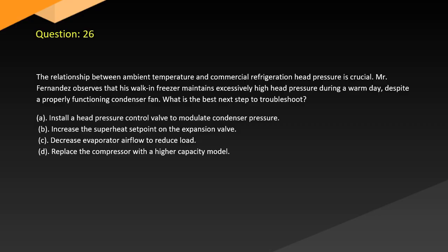Question 26. The relationship between ambient temperature and commercial refrigeration head pressure is crucial. Mr. Fernandez observes that his walk-in freezer maintains excessively high head pressure during a warm day despite a properly functioning condenser fan. What is the best next step to troubleshoot? A. Install a head pressure control valve to modulate condenser pressure.